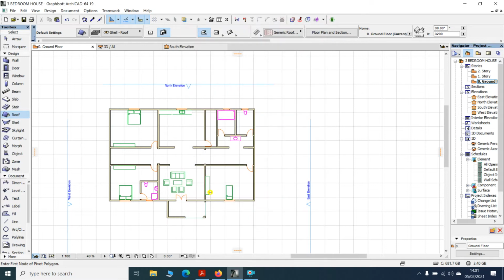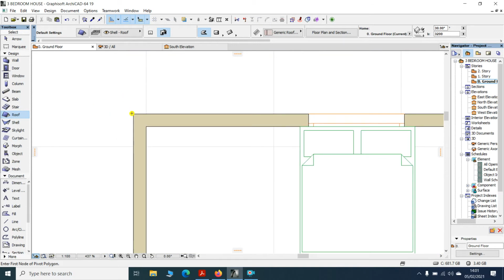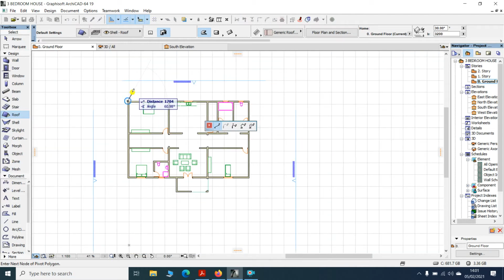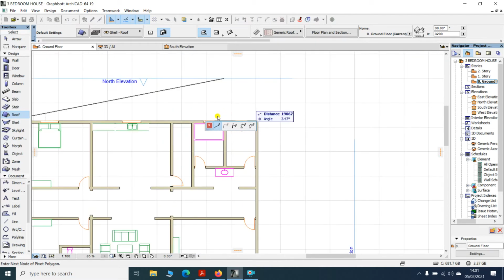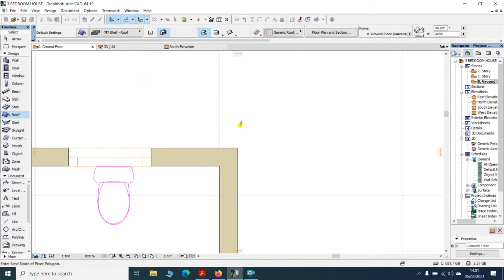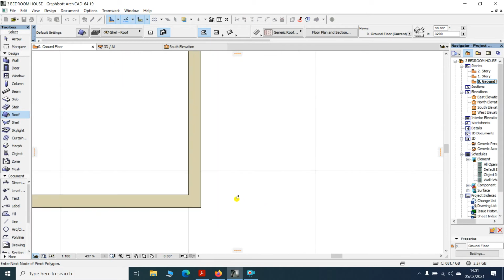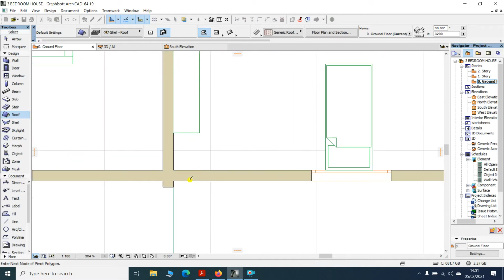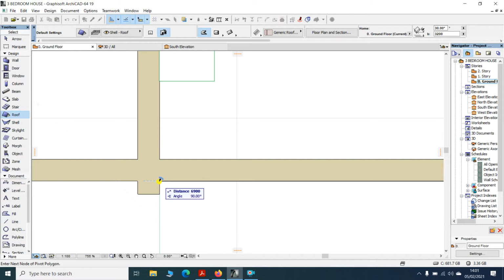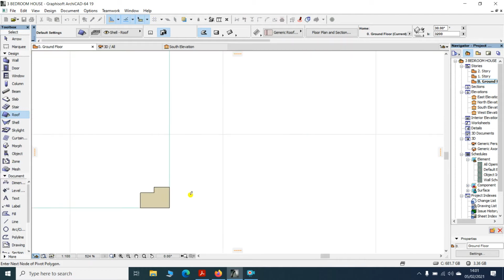then I click OK. And then for the construction method, you have to use complex roof, and then you come to the corner of the wall and left click. This is like how we place the slab. And then you go to the next corner and left click, you go to the next corner, left click, like that until you reach the point that you started from.